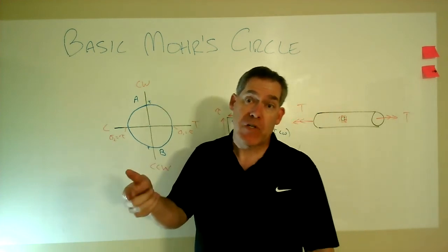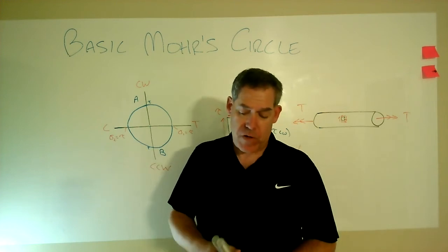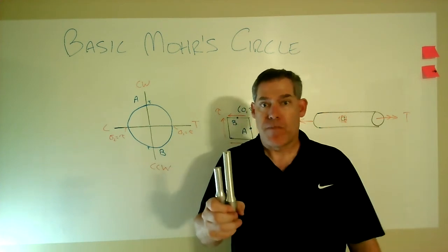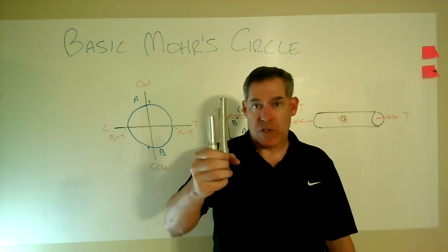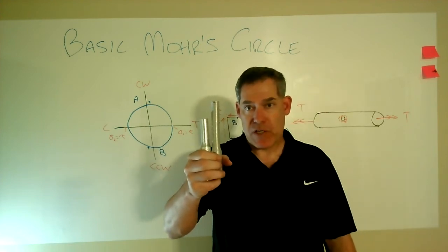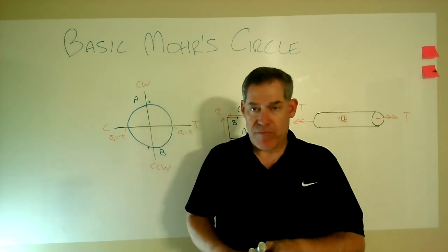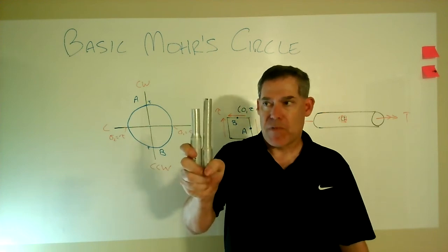Now they may eventually get to a brittle plane, but they will fail in shear first. That's what creates the ductility. Tension is breaking and rupturing those atomic bonds, whereas shearing is actually taking the crystal lattice structure of the metals and sliding it past itself, and that doesn't break the atomic bonds. That's why it creates this ductile kind of behavior.